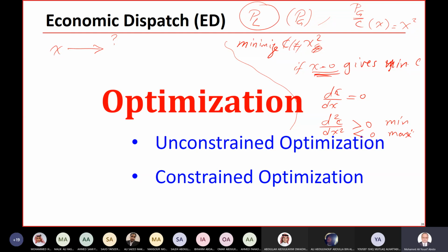And also if you have transformer taps, if the transformer tap is not 1-to-1, in this case you can also have some reactive power sources through this transformer tap, and this is also another source of reactive power. A reactive power problem is completely different from what we have here. Here we are targeting only the generator output power, the real power output of the generator.